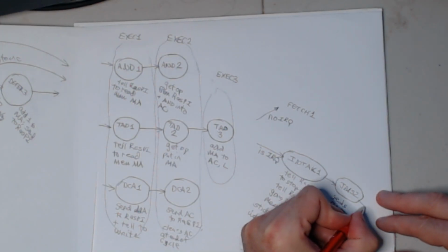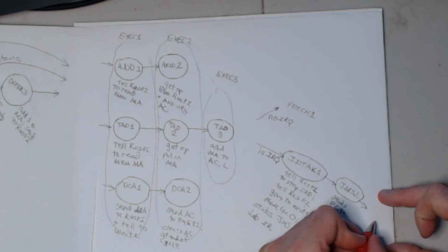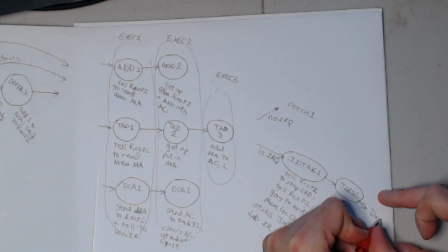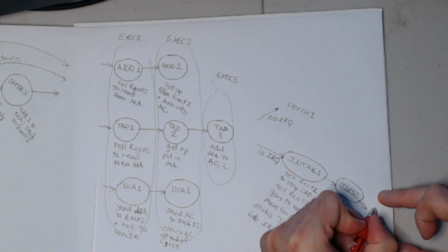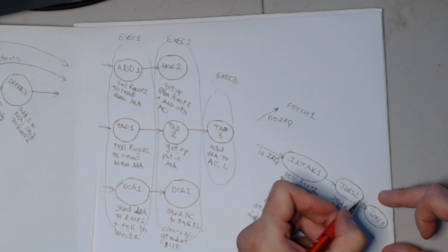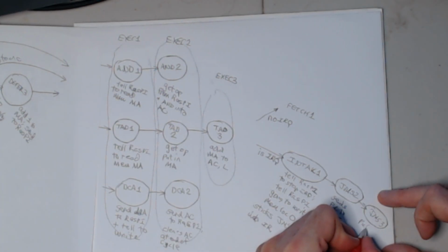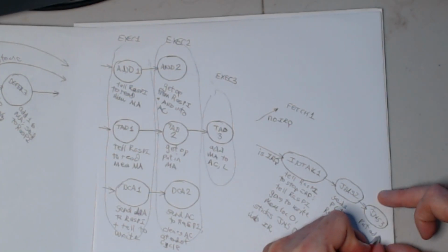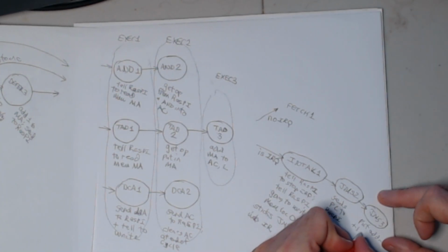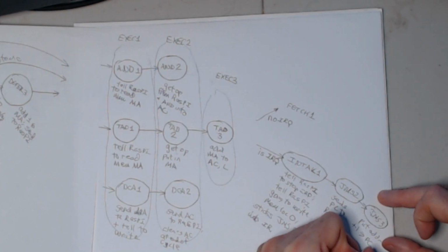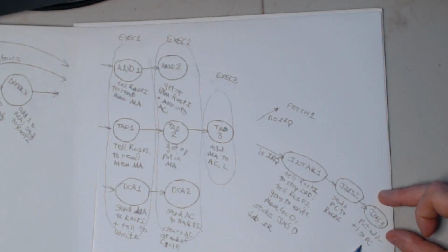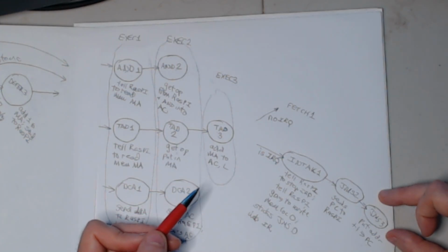And then JMS 3, right down here in the corner, puts the address plus 1 into the program counter. So that's what a JMS instruction does. We put a JMS 0 in there, so it'll end up with a 1 in the program counter, which is how a PDP-8